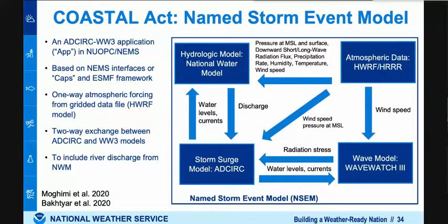From the surge side, the water level and current are advected from the surge model to the wave model as an input. On the other side of the system, breaking waves transfer their momentum to the ocean currents, and in our coupling system the wave model provides the wave radiation stress gradient as a source term to the surge model, as additional depth-integrated stresses. Then all of them are coupled and running together.